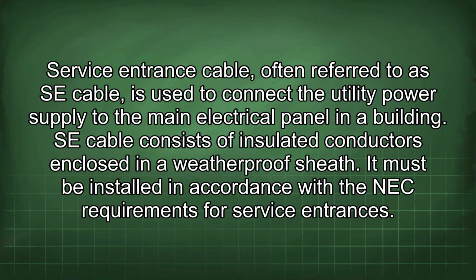Service entrance cable, often referred to as SE cable, is used to connect the utility power supply to the main electrical panel in a building. SE cable consists of insulated conductors enclosed in a weatherproof sheath. It must be installed in accordance with the NEC requirements for service entrances.